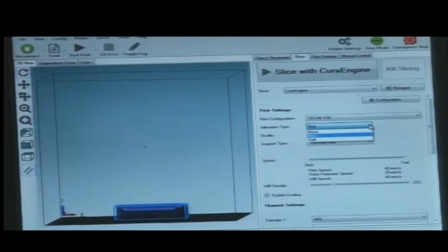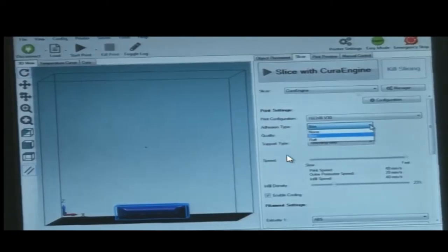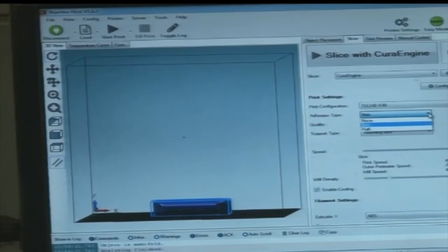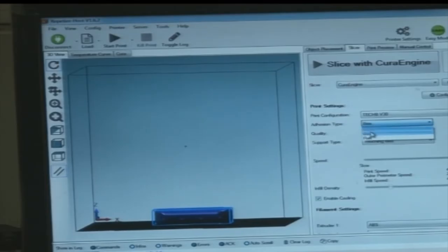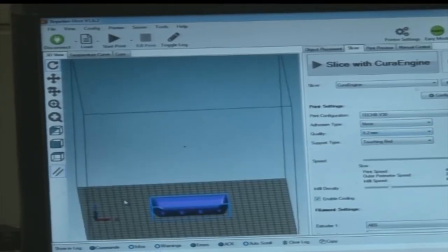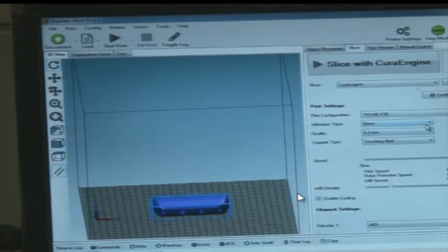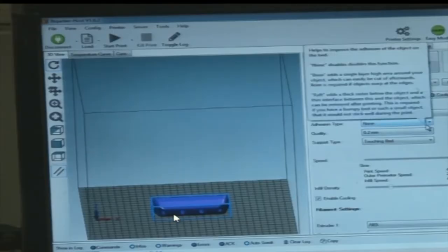It is actually known to the manufacturer that the quality of the product varies with using brim or not. In general, the brim command is preferred to reduce the wastage of the material. The second layer onwards would follow the CAD geometry. In this specific model, the brim and raft are only the first layer, as I mentioned before, but in certain machines raft can be more than one layer. So we have just kept it as none, that is, we are not getting any brim or raft here.